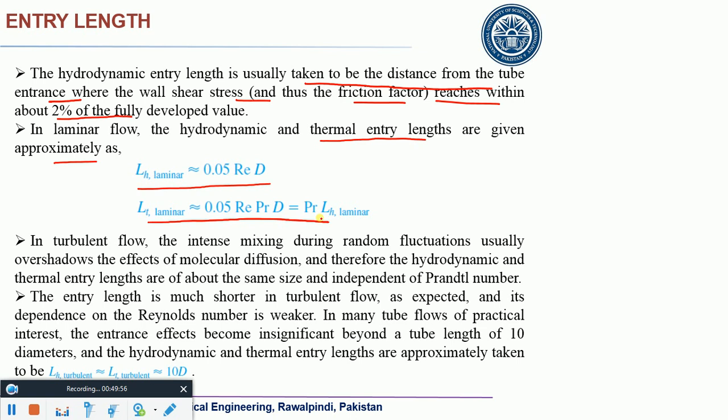So what happens in case of turbulent flows? In case of turbulent flows, it was observed that the thermal entrance length and hydrodynamical entrance length remain the same. Generally, most of the time they remain the same, and that value is almost equal to 10D.